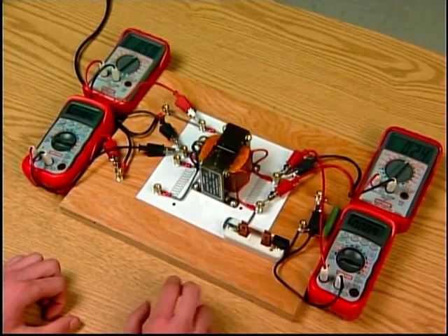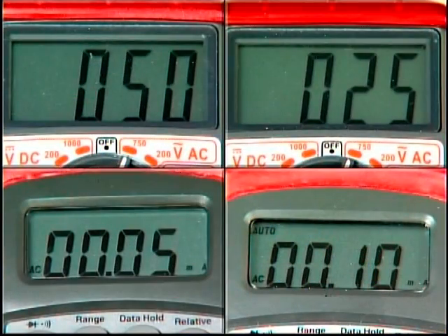Conversely, a step-down transformer produces a decrease in voltage and an increase in current. Transformers are classified as step-up or step-down only in relation to their voltages, not their currents. Since the voltages of a transformer are directly proportional to the turns ratio, the currents in a transformer are equal to the inverse of the turns ratio.